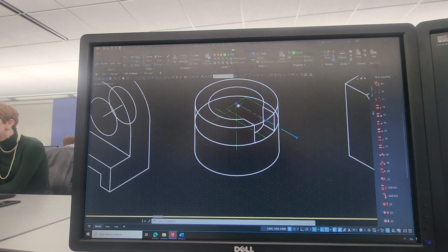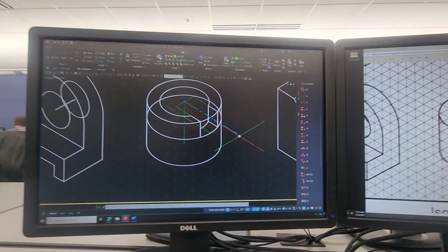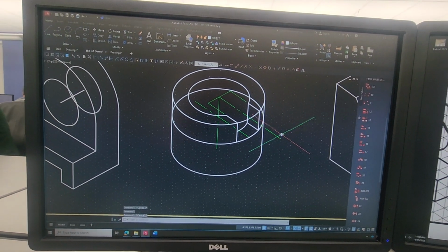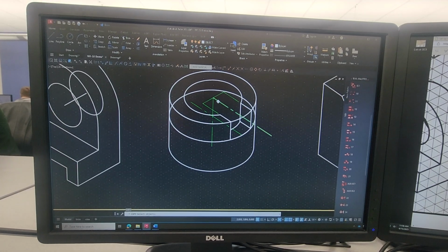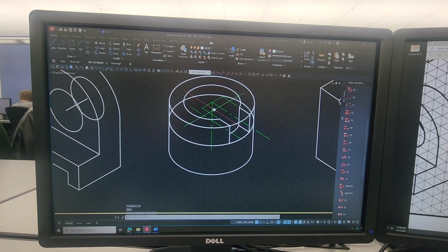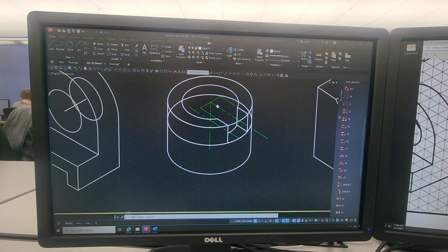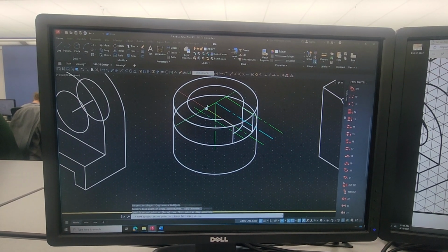I laid a line from that point and just drew it out here along the iso grid. Didn't care how long it was. Then I copied that line and created a line out here 1 unit. I created a line up there 1 unit. And I just simply copied that line and moved it from there to there. So you see what I've done? And there as well too.